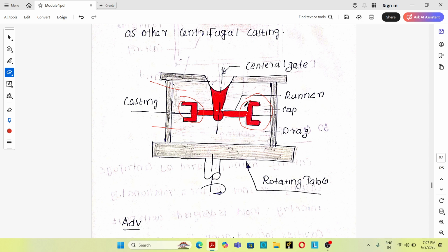As the mold is rotating, due to centripetal force, the molten material is forced into the mold cavities, which are located away from the axis of rotation. The centripetal force acting over the material during solidification is high, so a high density casting will be produced, and the impurities located in the center portion can be removed later by some methods.